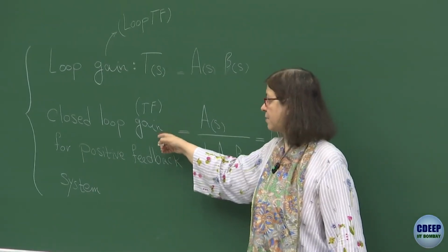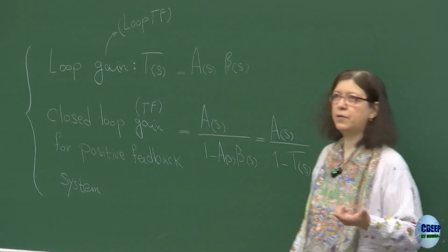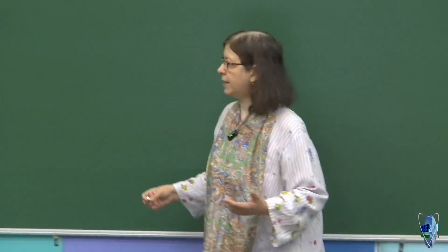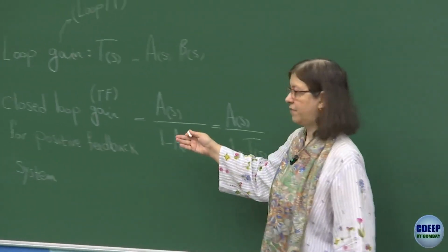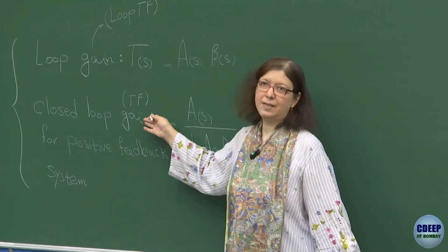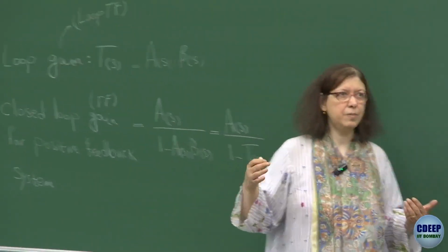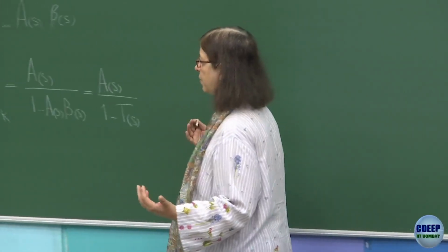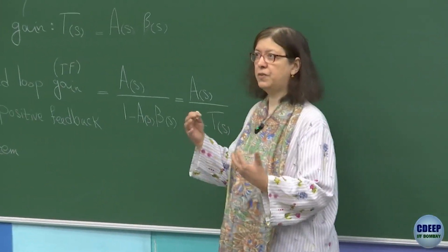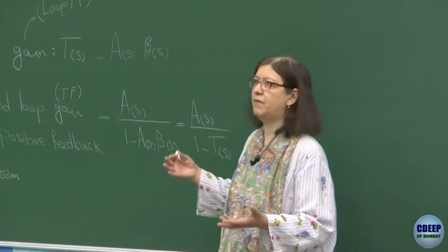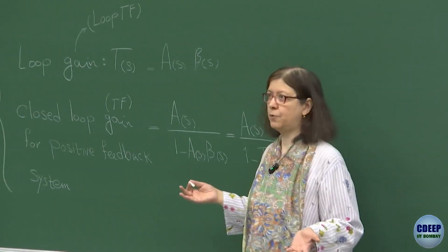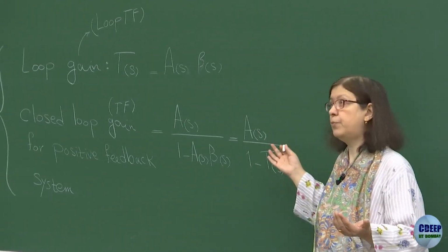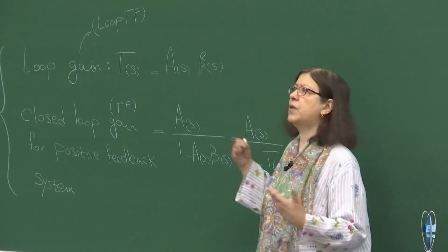Therefore, this transfer function in the specific case we were talking about is actually a transimpedance transfer function. It's not exactly transimpedance in general; it is transimpedance when you have the input current source and the output as a voltage at a given node. If you inject and get the output at the same point, it becomes effectively the equivalent impedance at that node. If you choose another point, it's fine, then it becomes transimpedance.